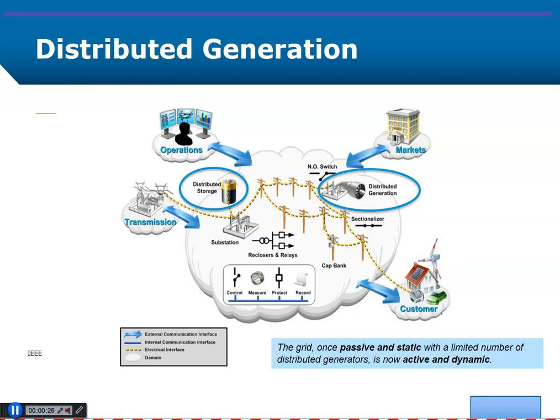Due to its size and location, DG sources are typically connected to the distribution network, that means the low and medium voltage grid. The size of the DG sources varies from a few hundred watts up to a few megawatts, or even a few tens of megawatts. Nevertheless, it remains at least one or two orders of magnitude smaller than the conventional centralized bulk power plants.